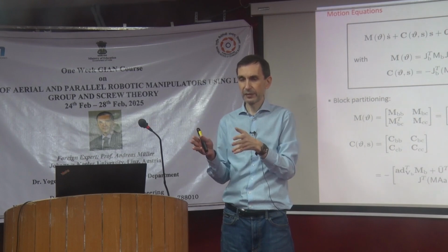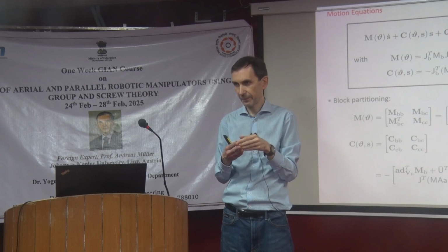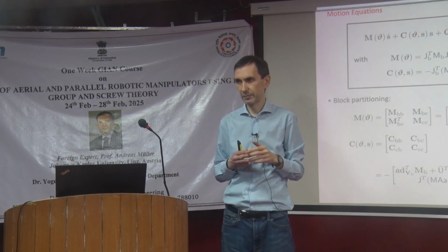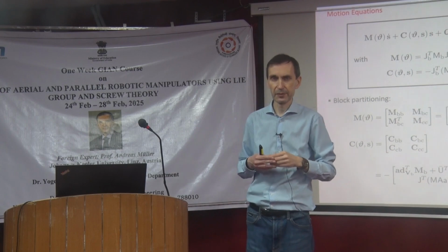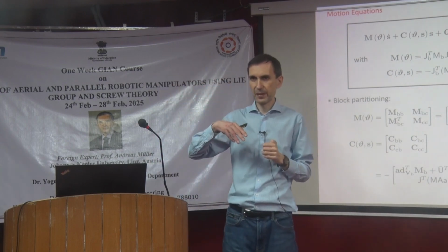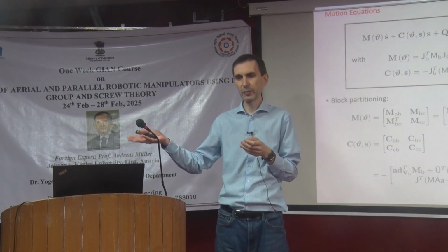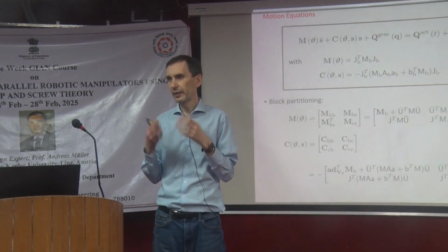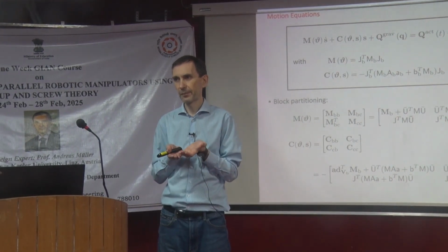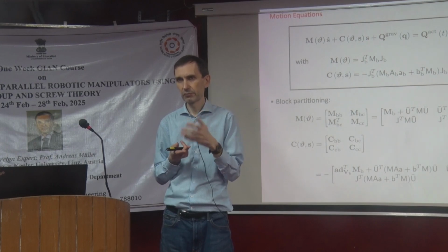By assuming that the damping and the friction and the stiffnesses are linear, which makes sense, you get a transfer function. From this you get a frequency response, and from this frequency response, you identify a linear model that comprises your stiffnesses, your damping, and that's it.